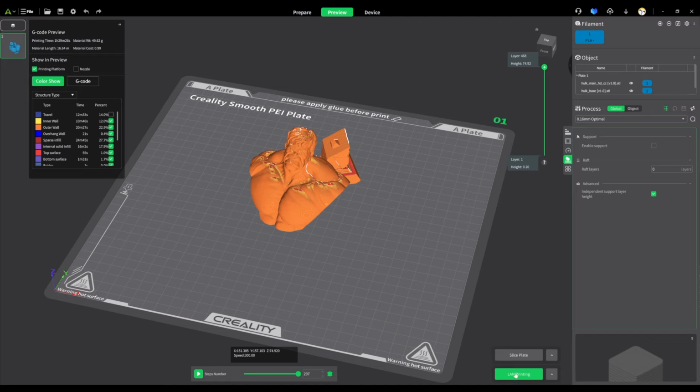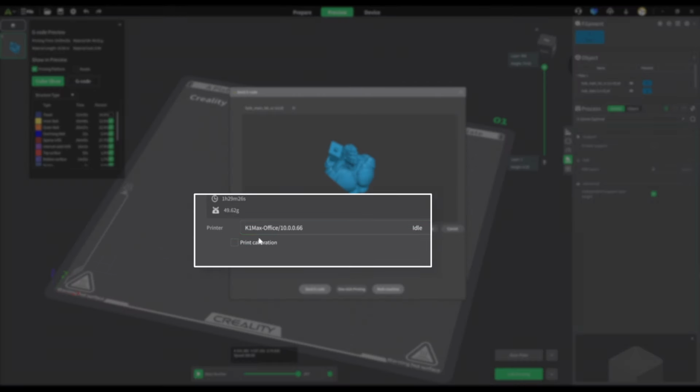So on Orca, you have basically all the options for the slicer functions that you have inside the Creality Print 5, but having the possibility to operate the printer directly from the software is better, and you have just one function that you will not have an alternative outside of Creality Print 5, that is sending your G-code with instructions for running calibration right before the print. So this is the difference between the calibration you run directly on the printer and sending the calibration flag.